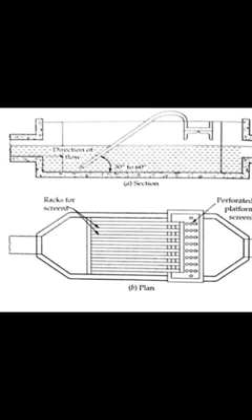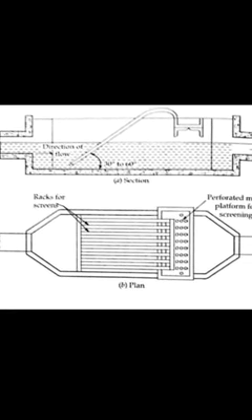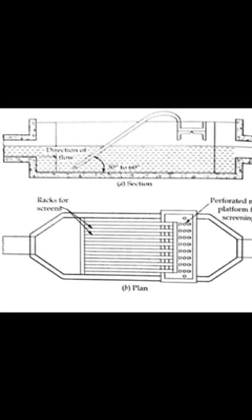So that will be this. Whatever I'm showing, it has an opening range of 5 centimeters to 10 centimeters. That will serve as a protecting device, usually in contrast to a finer screen, which functions as a treatment device. These bar screens are usually handy, and they will be cleaned.